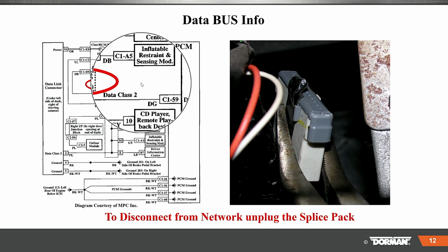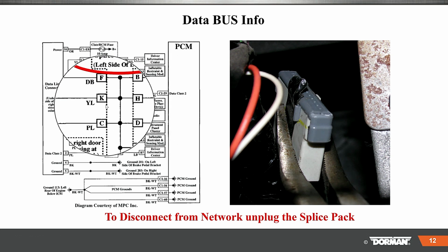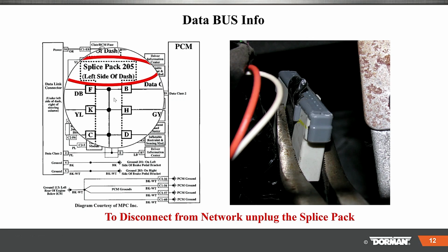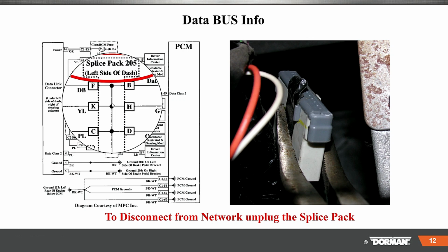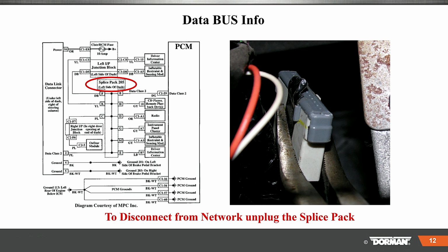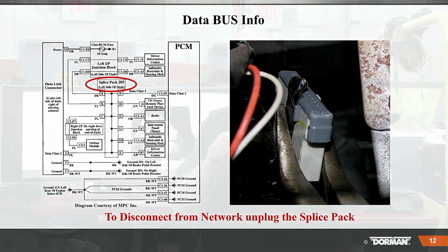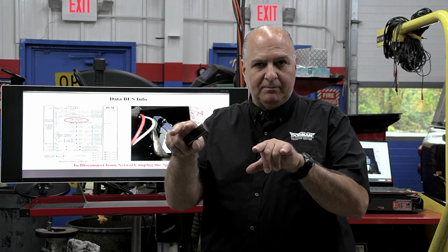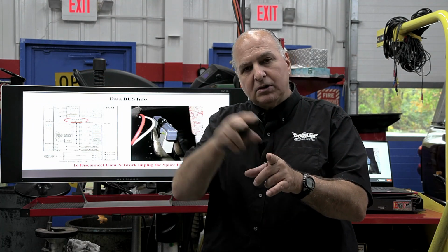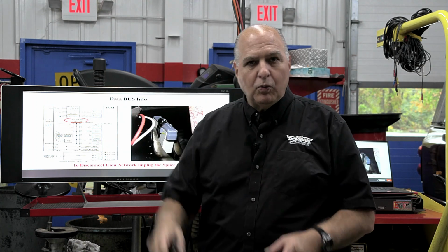So let's say you had a problem, okay? If you had a problem on the network and you pulled the comb out and no longer have a network, how do I find out where I have the problem on the network? We would then get a jumper wire and jump it one at a time to see if that particular one is bad. They do make a set of wires that you can plug multiple in. You go into one and then you could go out and do 2 or more